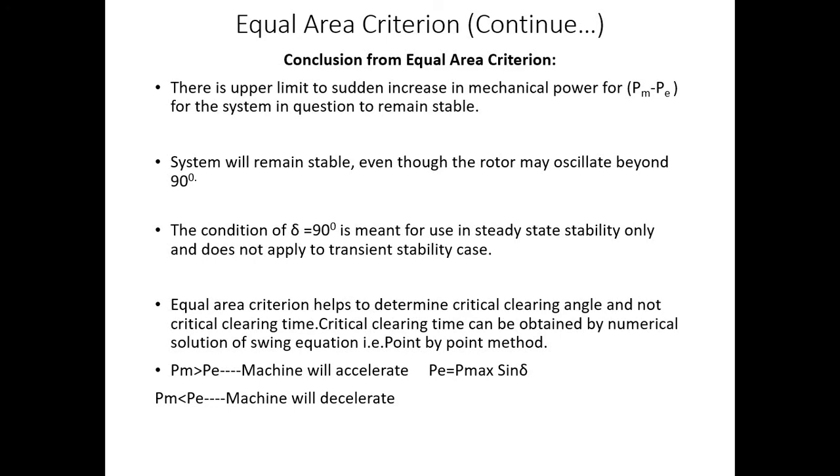Thus the equal area criterion helps to determine the critical clearing angle and not the critical clearing time. The critical clearing time can be obtained by numerical solution of the swing equation, such as the point by point method, but it is not part of your syllabus.